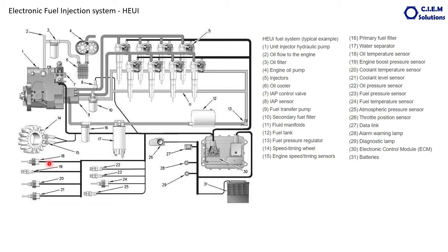It measures what amount of inlet air is being passed inside the engine. If the inlet air pressure is more, more quantity of air is entering the cylinder. So how much air is entering and how much fuel is required for efficient burning of that particular quantity of air, this sensor sends the quantity of air being charged in the cylinder.